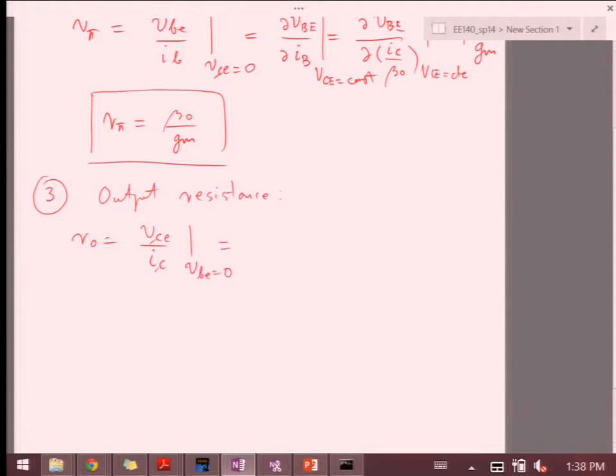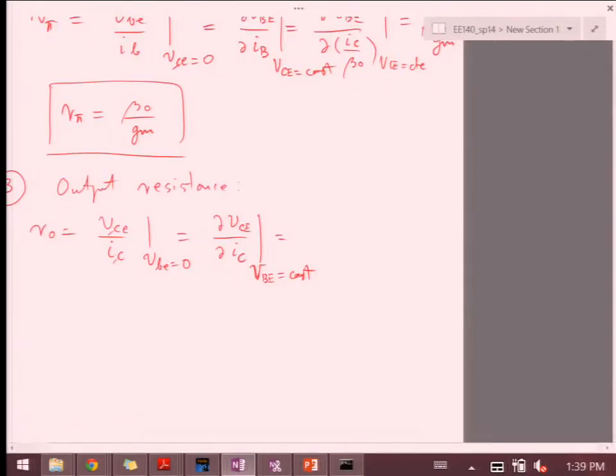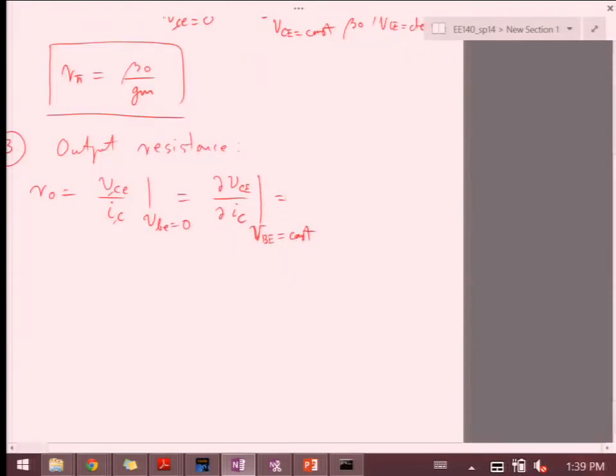And that's going to translate into changes in large signals, given that VBE equals constant. And again, now I can go and do a derivative on the full formula, so I can draw it as 1 over delta IC over delta VCE. And we've already seen what this is, delta IC over VCE, right? When we talked about early voltage effects, that's exactly what we're looking for.